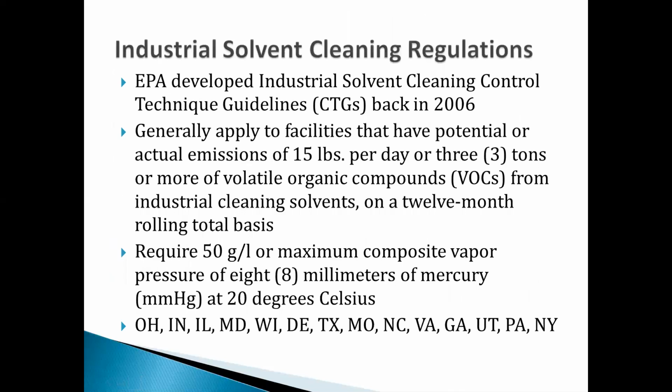And then the last slide I have today, I wanted to talk about industrial solvent cleaning regulations. Where coatings are applied, we of course have the HAP and VOC standards for the actual coating, but any spray guns, any storage tank, any lines, essentially any general cleaning that would occur in that facility could now be subject to so-called industrial solvent cleaning regulations.